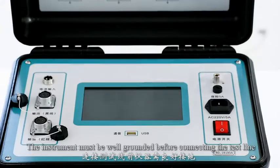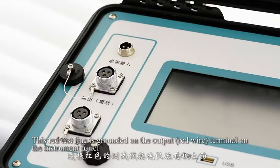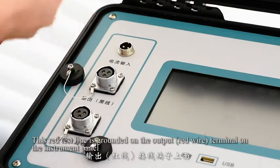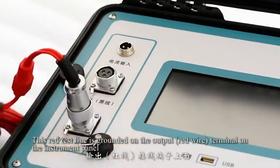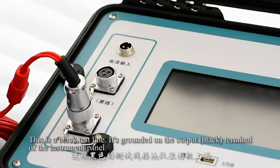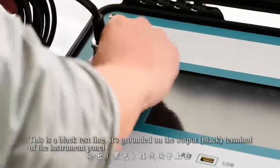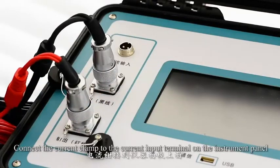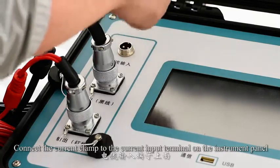The instrument must be well grounded before connecting the test line. This red test line is connected to the output terminal on the instrument panel. This is a black test line. It is also connected to the output terminal of the instrument panel. Connect the current clamp to the current input terminal on the instrument panel.